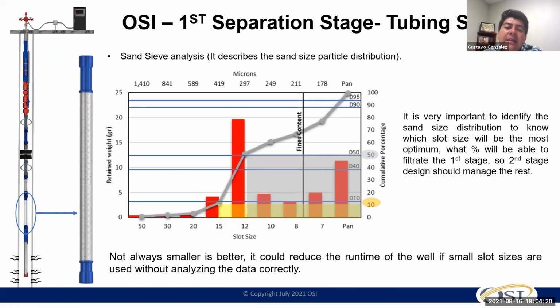And the reason behind that is because the sand that you're collecting in the tailpipe, because you have a desander, is more the sand that has been captured inside. The sand that goes through the pump, and the sample that you're getting from there, is sand that has been crushed by the stages when it's passing through at high velocity and high pressure. And the sand that is above the discharge of the pump is sand that was already crushed and is now flowing to the surface. So based on that, we analyze the sand that we're dealing with.